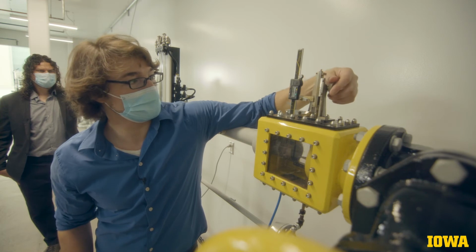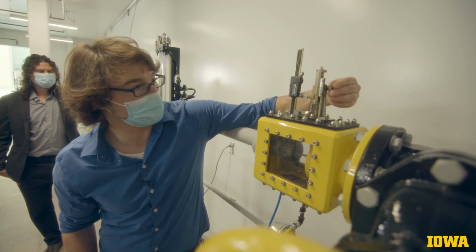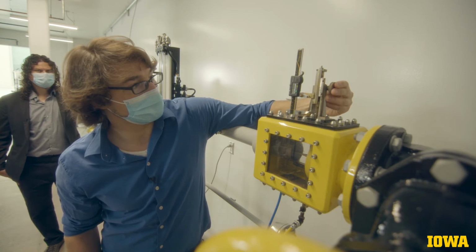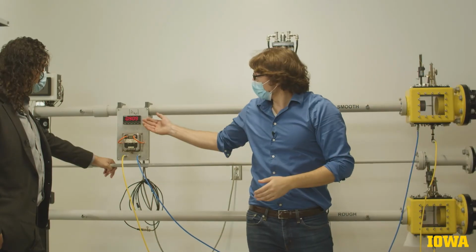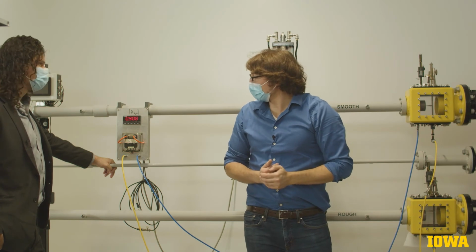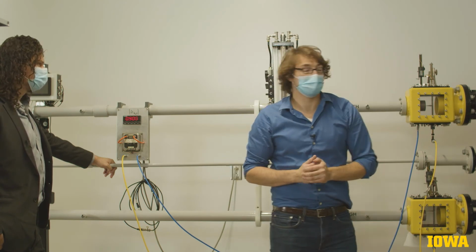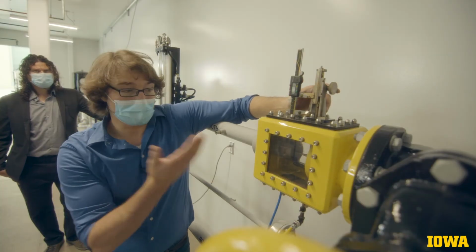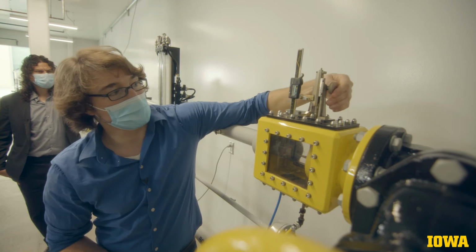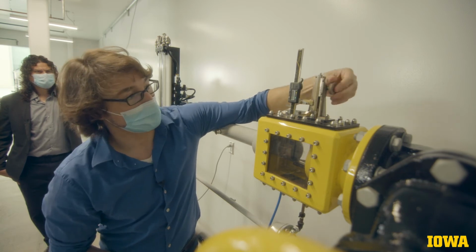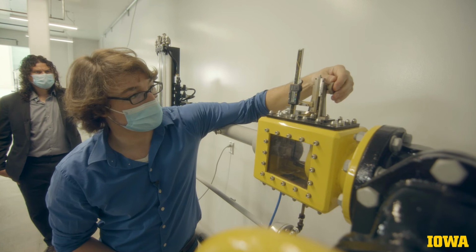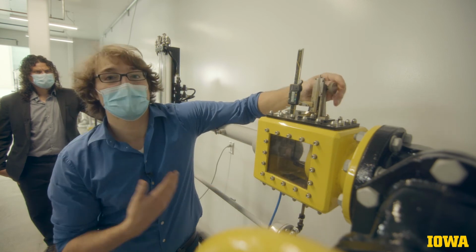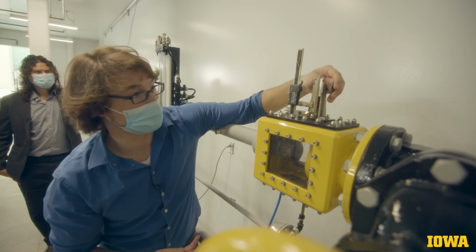Moving back to center line to obtain our center line measurement at 0, we get 0.908 feet of water. Now the repeated measurements are going to be acquired at the edge of the pipe, or at 24 millimeters, where we will move the probe into place, obtain a measurement, move it away, replace the probe, obtain another measurement, for a total of 10 replicated measurements.